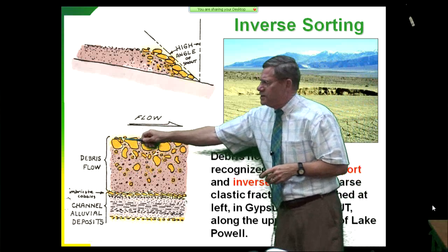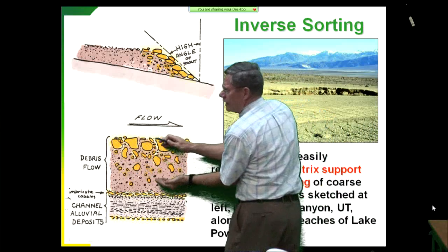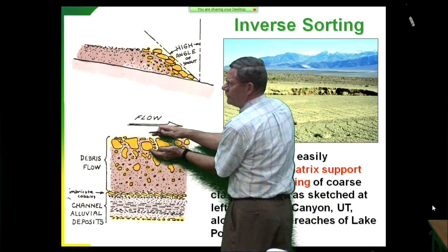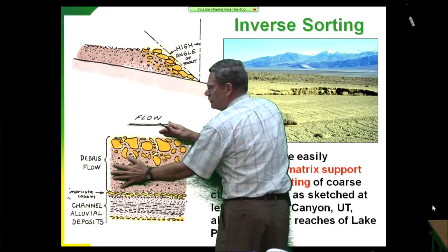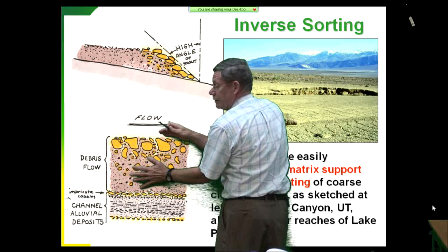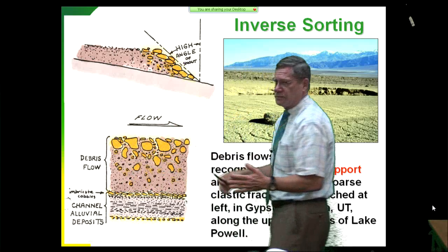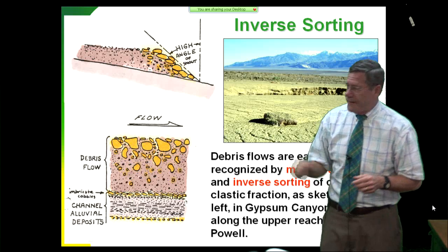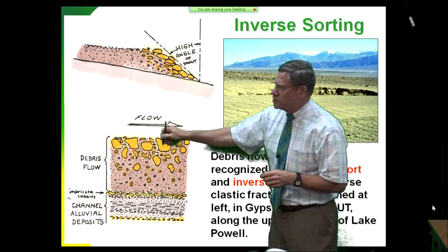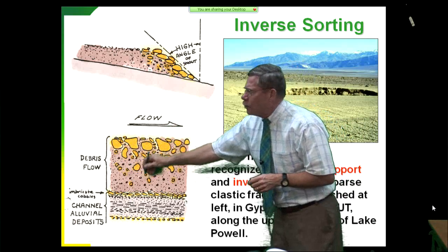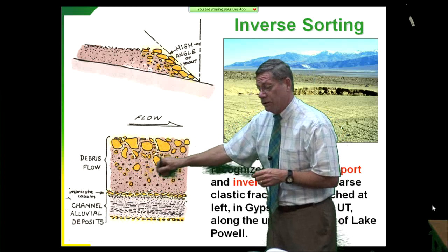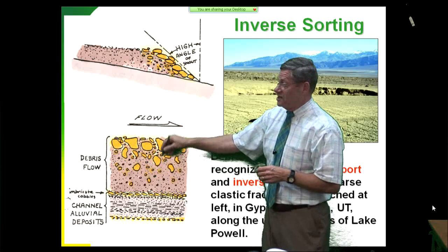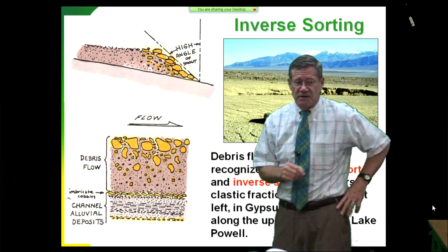But you tend to get these bigger boulders that get floated up through high uplift because this is not water, this is a slurry. So Archimedes' principle is much more in effect here. That boulder weighs its dry weight minus the weight of the fluid or the slurry that it's in. Well, that slurry is not 62.4 pounds per cubic foot.